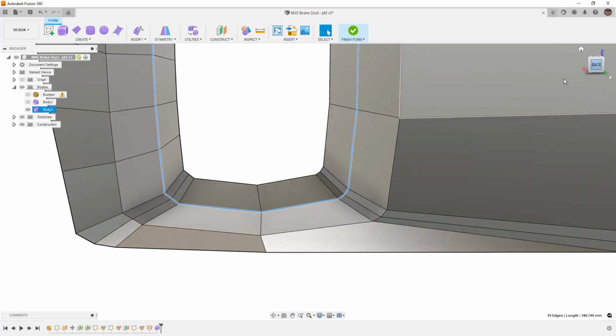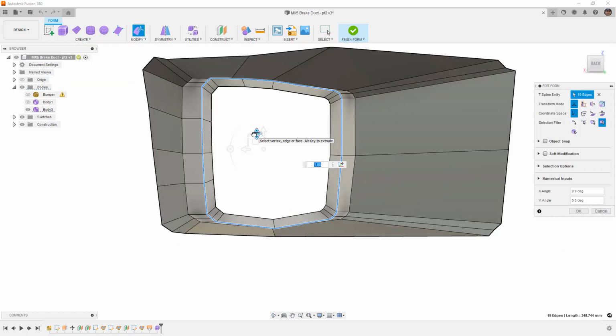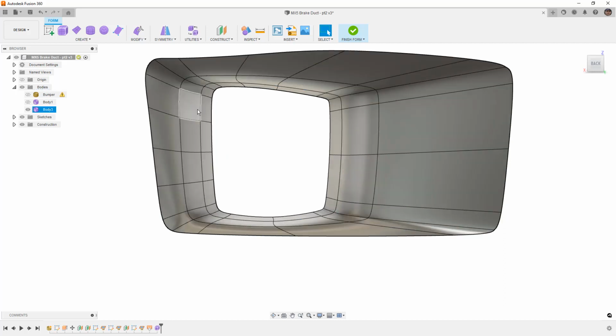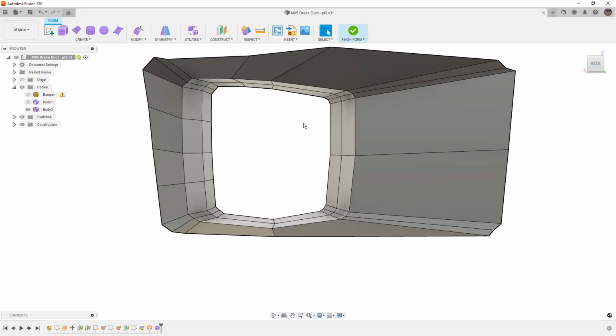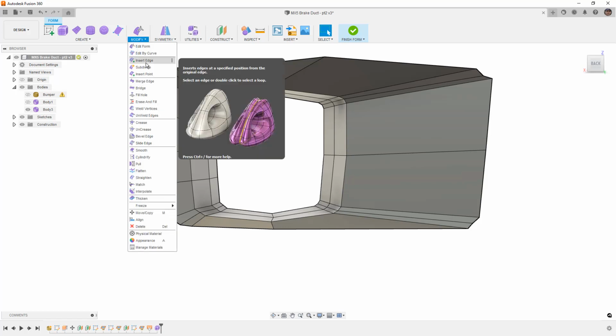So in this case, when I'm looking at box display, I want to manipulate this by scaling it down, and I want to see consistent transitions between everything. Once I'm happy with the way things look in box display, then I can start worrying about smooth display, making sure my corners are correct, making sure it fits the shape that I want. After all that is done, if I want to move into more detail in certain areas, then I need to start dividing it up.